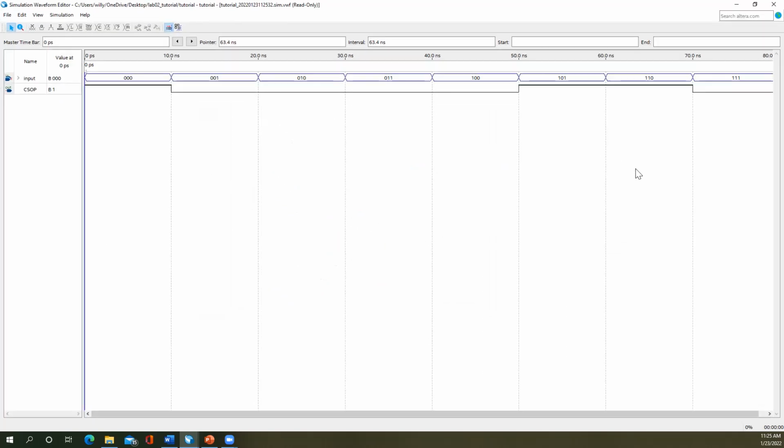So we said this circuit was a product of minterms 0, 1, 5, and 6. I've got an error. Note that 0 is a 1, 5 is a 1, 6 is 1, and 2, 3, 4, 7 are producing zeros as outputs, but we're getting an output of 0 for our combination of 0, 0, 1. That's not what we expected.